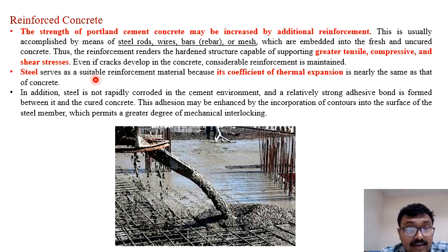Steel serves as a suitable reinforcement material because its coefficient of thermal expansion is nearly the same as that of concrete. In addition, steel is not rapidly corroded in the cement environment, and a relatively strong adhesive bond is formed between it and the cured concrete.